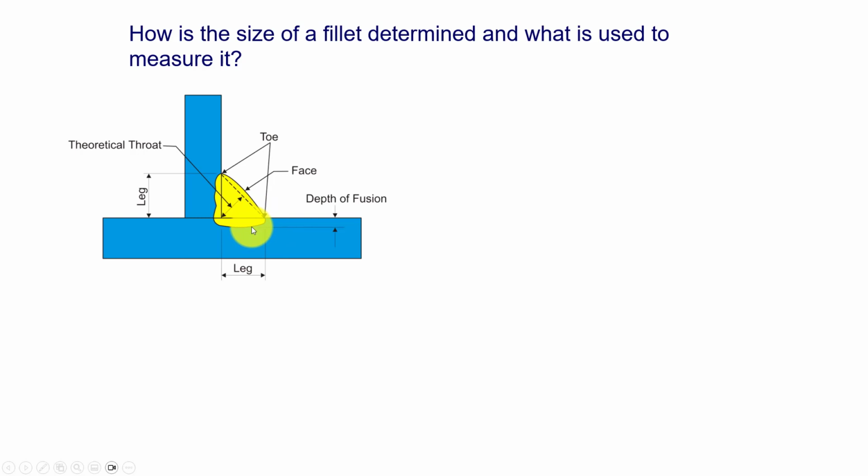We're also interested in the depth of diffusion on this. So again, we're going to be looking at maybe how the material, the heat from the fusion, the weld ties into these, and that we don't have any cracks or overlapping of the materials as well.